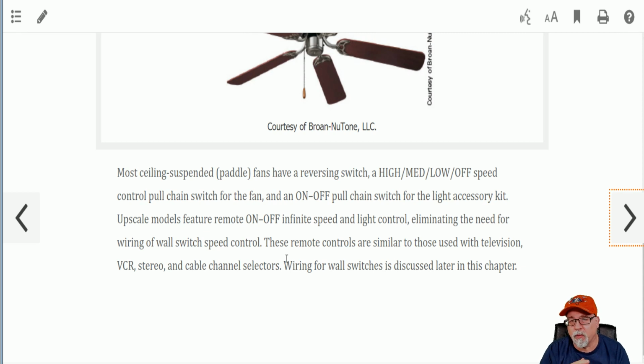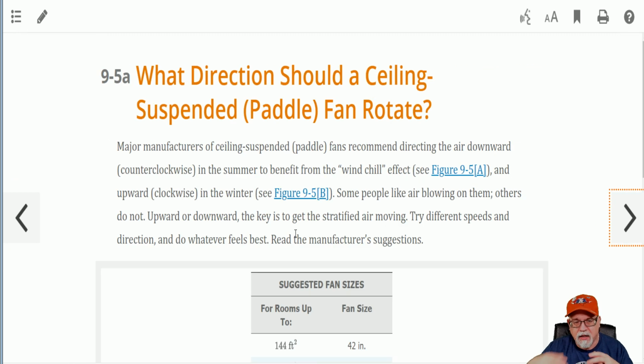So it doesn't matter whether you run a 14/3 up there or not, like it used to be. Now it's going to be a 14/2 up there if that ceiling fan is in a location where you could plausibly put a ceiling fan. Now, if that light box is for a sconce or track lighting near the wall, then it would not require this because the blades would hit the wall. So that's the allowance that says that's not plausible. But anywhere else, if you could put a ceiling fan there and the blades wouldn't be inhibited, then you're going to have a box that supports the weight of the ceiling fan. Of course, we talk about that throughout the unit, and many other units get into a lot more detail than that, but I just wanted to give you that thought.